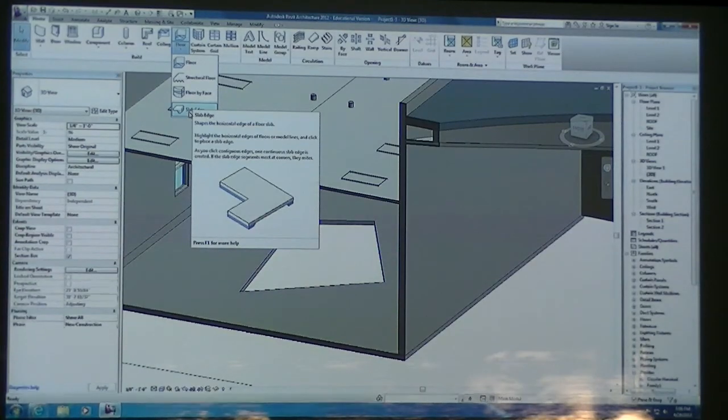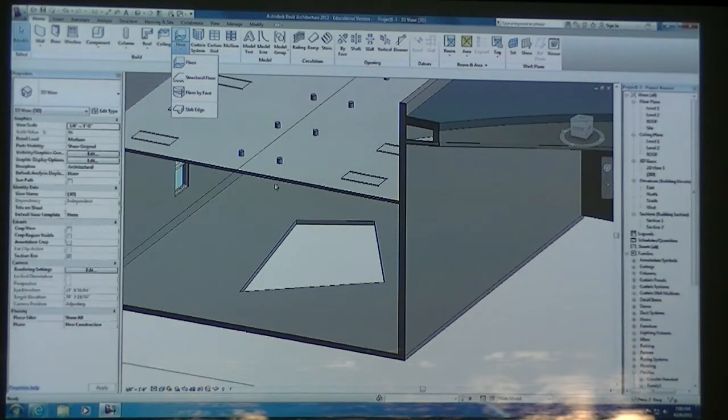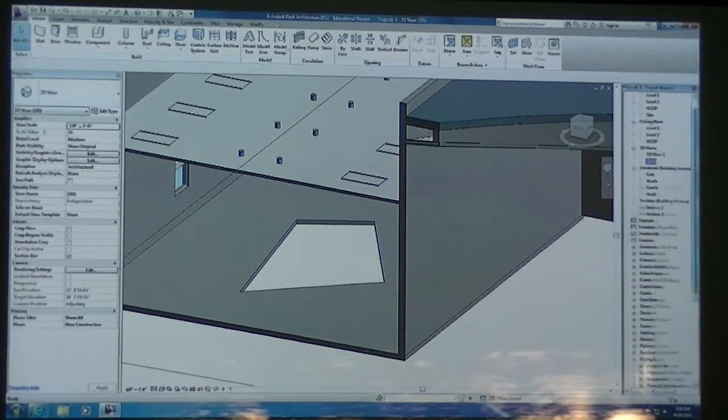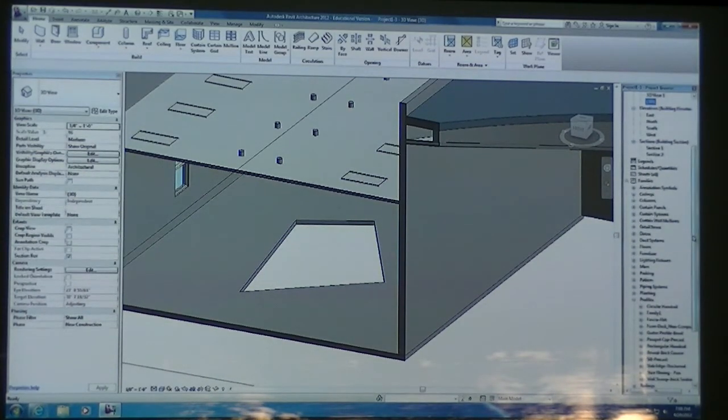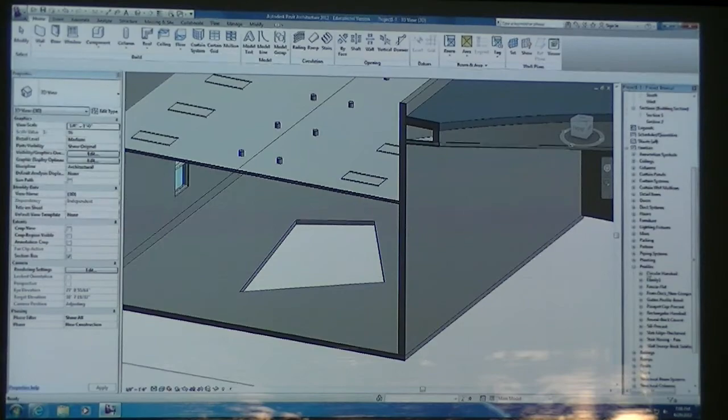Now, we're not quite there with our hotels because we've got a lot of elevated floors. So more likely, we're going to have to customize our own slab edge. And slab edges work in the same way as our rail types that we've gone over, how to do railings and customize those railings and mullions and all of that. It has to do with families in our project browser, under profiles. You're going to create some kind of section profile through this edge, and that's going to be a 2D element that eventually gets extruded along this whole entire slab edge path.